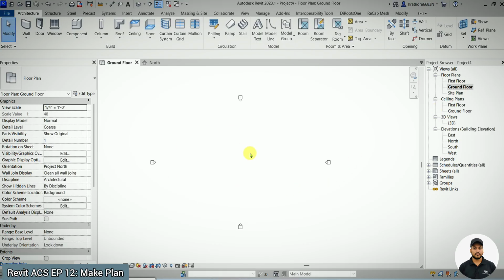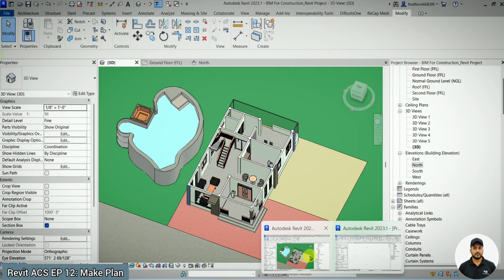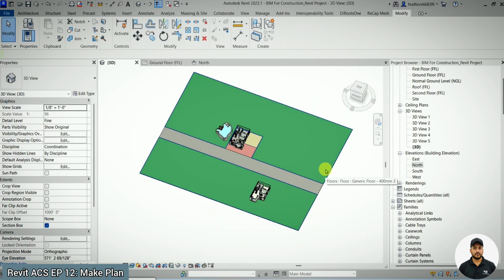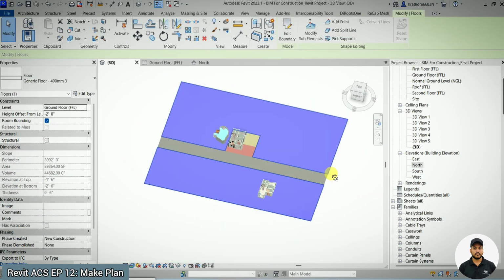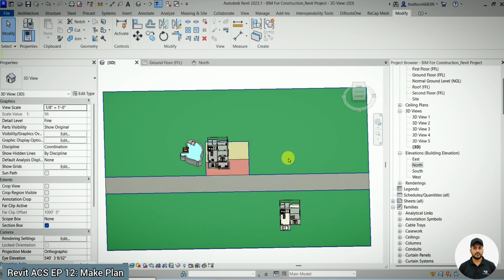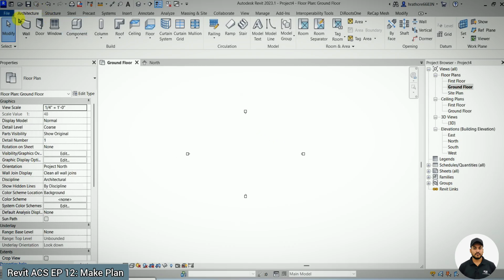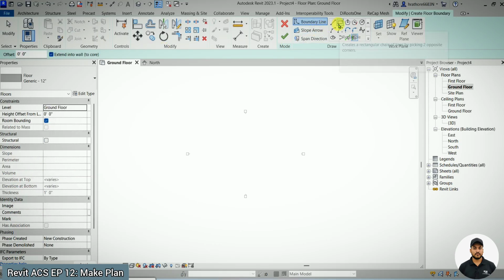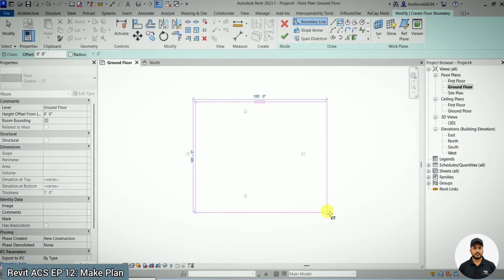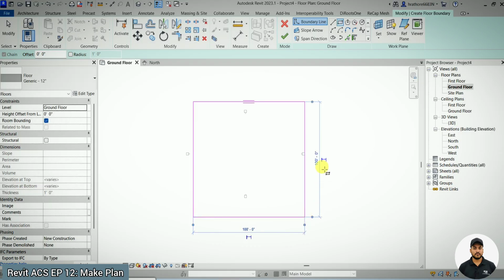So first of all I will set up topography. You can use the topography feature, and you can also create a floor, then you can paint it as grass. So first of all I will create this grass around this building plot, then we will start the modeling. For this I have to go to Architecture, then select Floor, Architecture Floor I am selecting for now. Then I will choose the rectangle option here. Okay, so this much, 100 by 100, I have created.